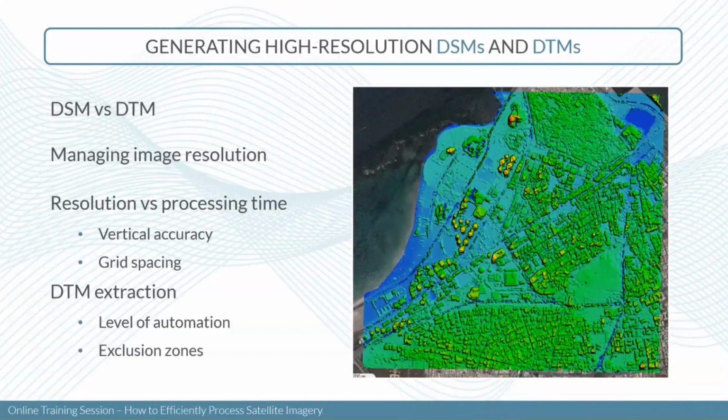But for this purpose, we're going to be able to extract the terrain model directly from the surface model with an algorithm that's going to try to remove much of those buildings, cars, and all those other elements. So in Correlator 3D, the first step will be to generate a surface model from the input imagery, as we can see here on the right side of your screen.